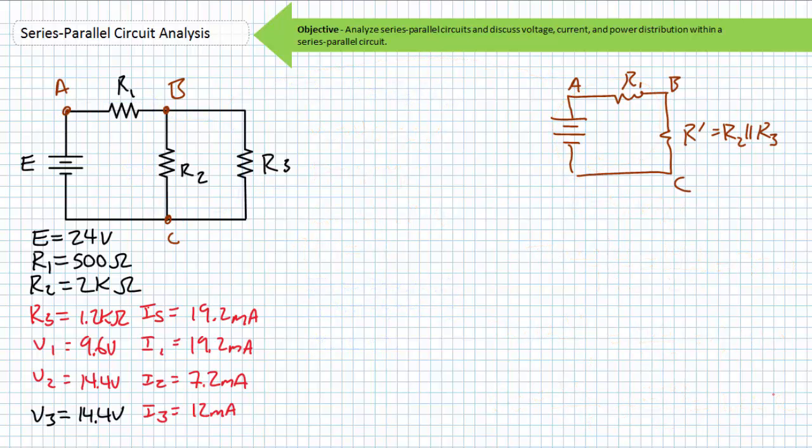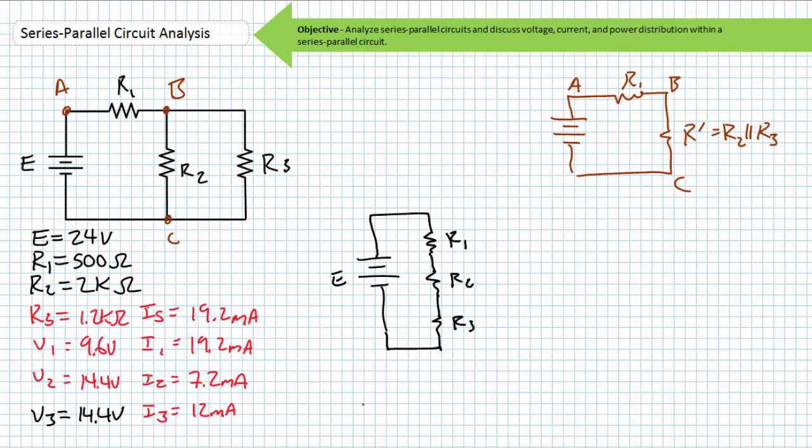Before we move on to the next illustrated example problem, let's consider the effects of shorts and opens inside series parallel circuits. It may help us to again refresh the differences between basic series circuits and basic parallel circuits when encountering these two errors. A shorted element in a series relationship will remove the shorted element only from consideration. No current will flow through the shorted element and no voltage will be dropped across the shorted element. This being said, since the shorted element has been removed from consideration and no longer presents opposition to the source, current through the series circuit will increase.